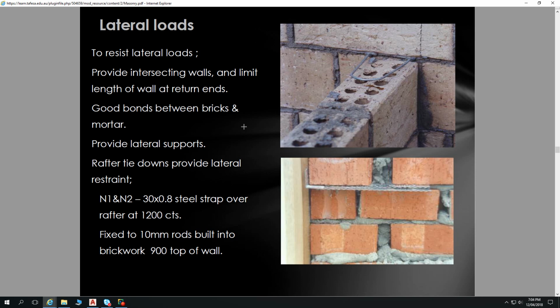So provide 40 millimeters coverage to each end of it, and it's set in there. And then later, because you know the locations where your rafter is going to come from the building plans, you wrap your strap around that later on. So doing that, drilling in and tapping the rods in, that's what you do retrospectively.